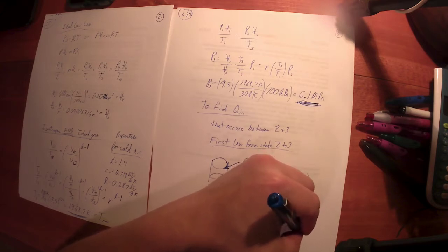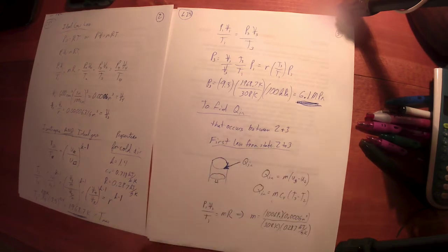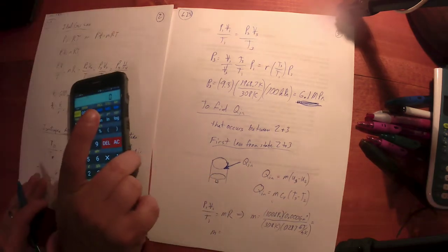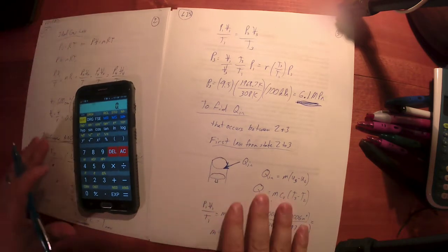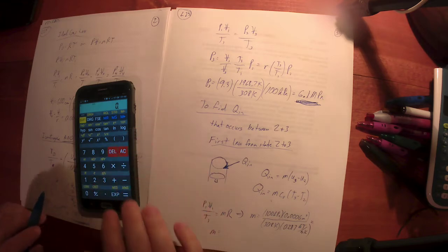That is kilojoules per kilogram Kelvin. Now the kelvins go away. The kilojoules is kilonewton meters, and the kilopascals is kilonewton per meter squared. So on top I've got kilonewton meters, and on bottom I've got kilonewton meters per kilogram. So the kilograms goes to the top. I'm left with a very small number. I'm going to write it on the next line. So I'm left with kilograms as my units.